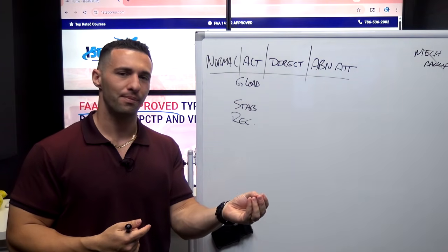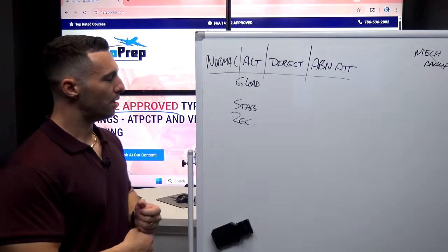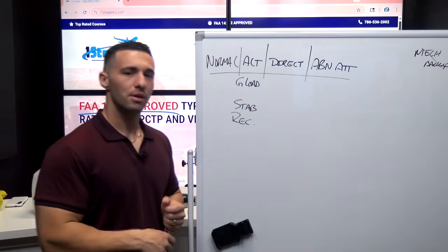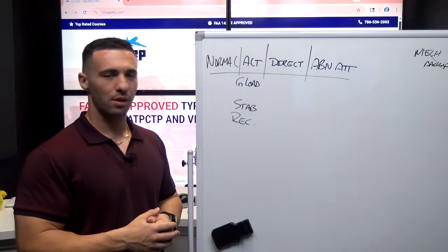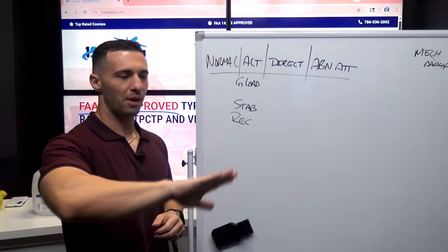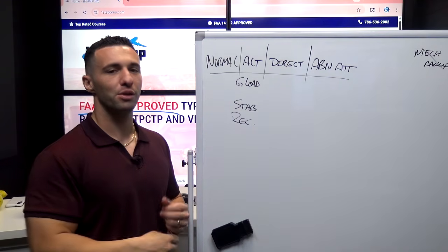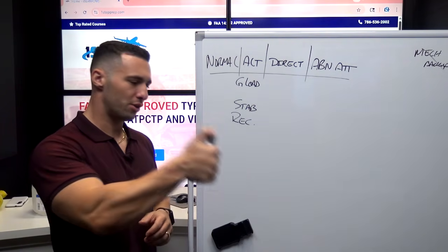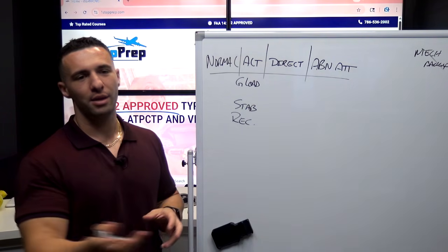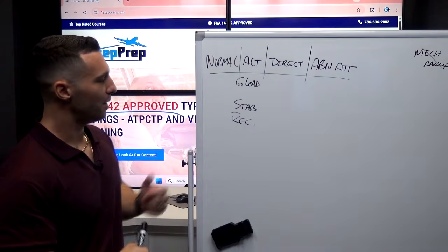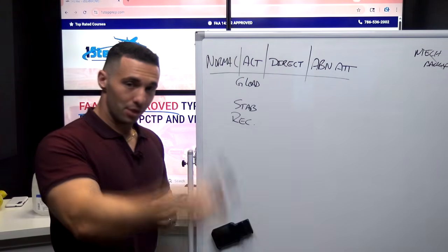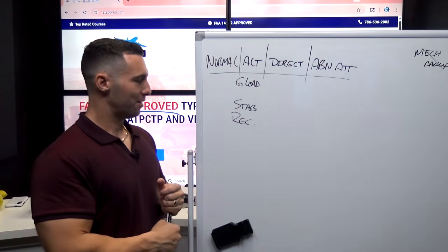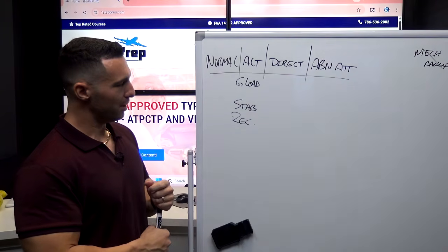The second one that we do is in alternate law. We force the jet in alternate law, and we give you a bank, 20 degrees usually, 1,000 foot per minute climb, and the recovery is at the low-speed stability. When you feel the nose pitching down, that's when we say stall, I have control, nose down pitch control apply, and then we level the wings, right? So big emphasis on lowering the nose, obviously. So that's your stabilities there.